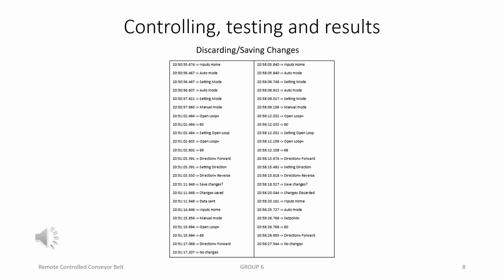It should also be noted that at first the Easy Transfer library was chosen for Bluetooth communication, but due to its incompatibility with the given microcontroller, it was determined that software serial would have to be used instead, meaning that only one bit could be sent at a time, and that outputs could not be viewed on the remote, as this added functionality required the Easy Transfer library.